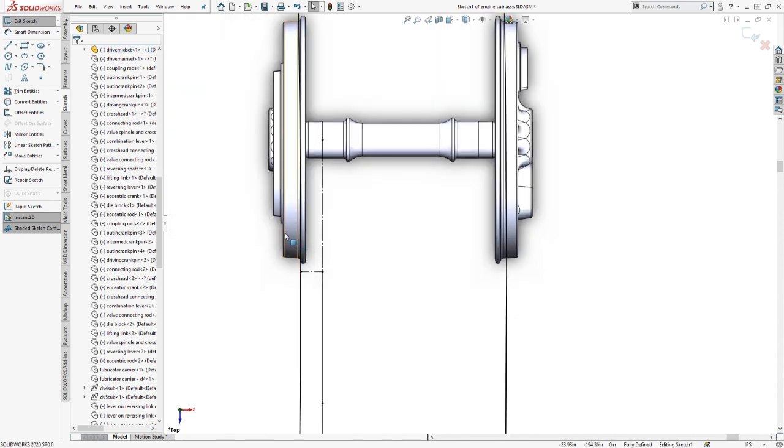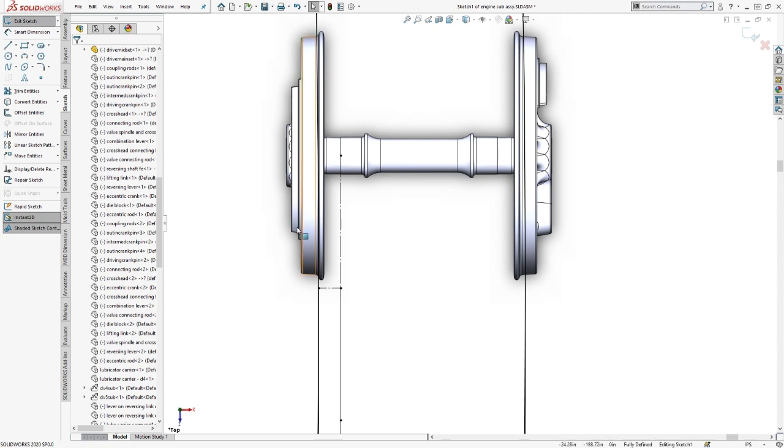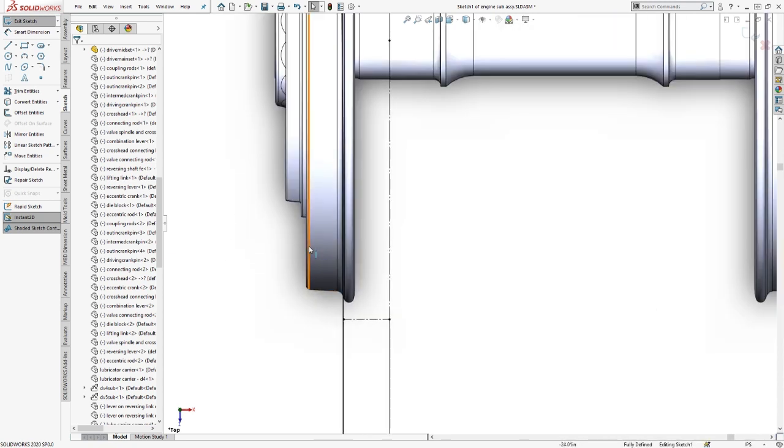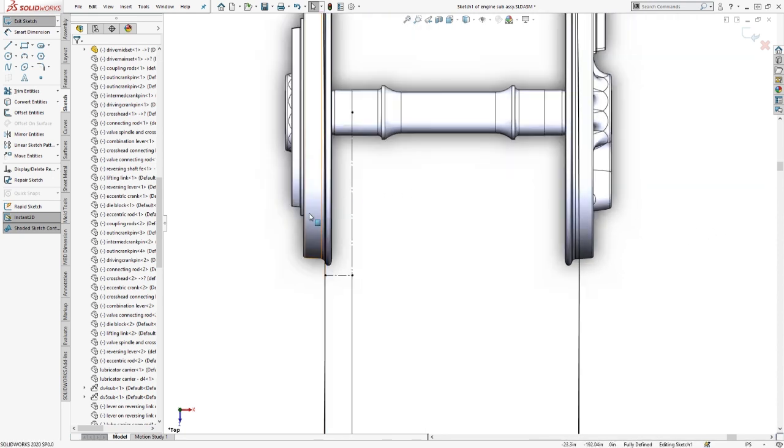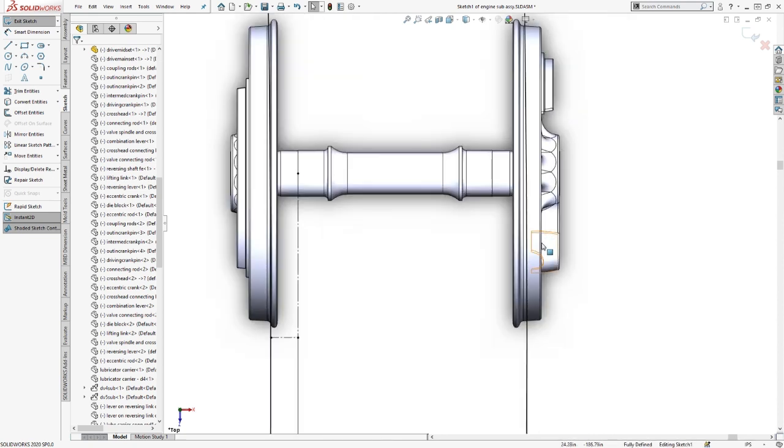So what's going to happen in a curve left to its own devices is it's going to find an equilibrium point, and the driver on the inside of the curve is going to tend to ride with the track toward the outside, where the diameter is smaller, therefore the circumference is smaller, the distance it travels per revolution is smaller, while the outside is going to tend towards the inside of the cone, where the diameter is larger and therefore the circumference is larger.